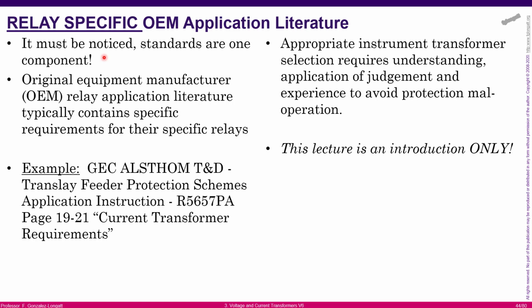If you are in a design stage, you can use the standard, because the standard is something that will happen and is realistic. But if you are in a real power system and you are working and dealing with real protections, the best advice is that you take into account the recommendations and instructions provided by the original equipment manufacturer. What I'm trying to say is that all those famous brands, ABB, General Electric, Siemens, and so on, all of them spend many hours running tests on their equipment, and they know at the very end all the characteristics and the performance of their equipment. And for that reason, it's a good idea to take their advice and go inside those documents.